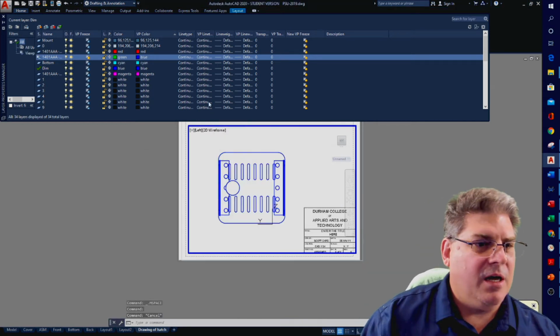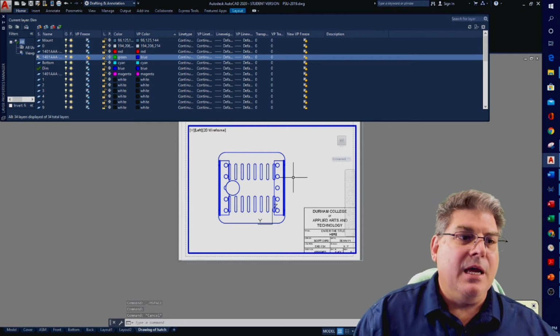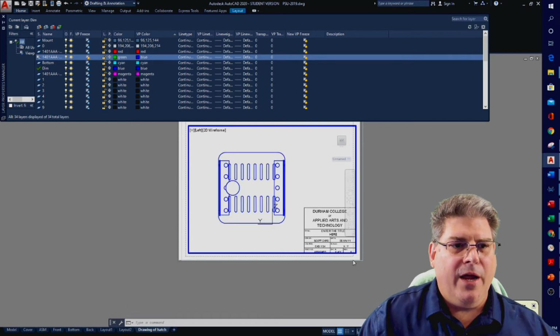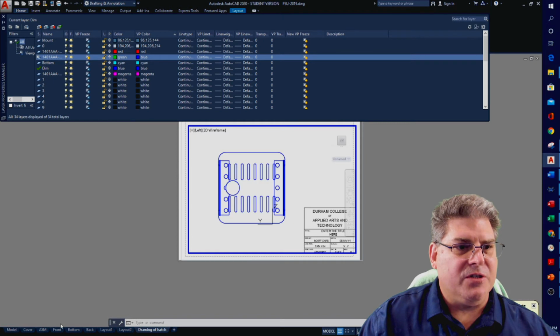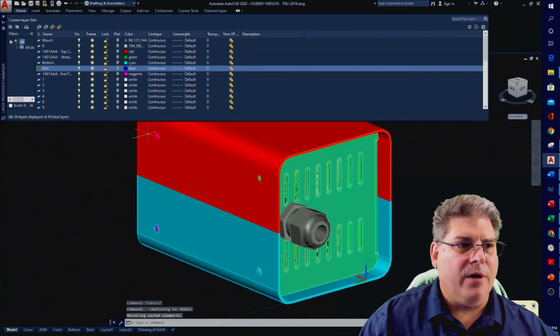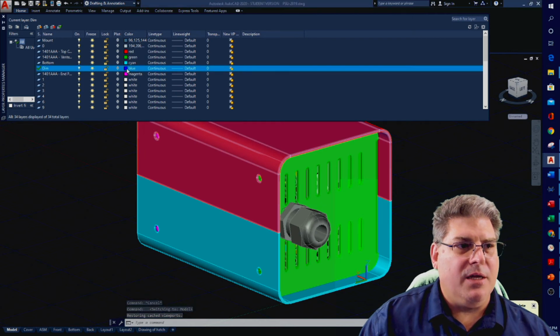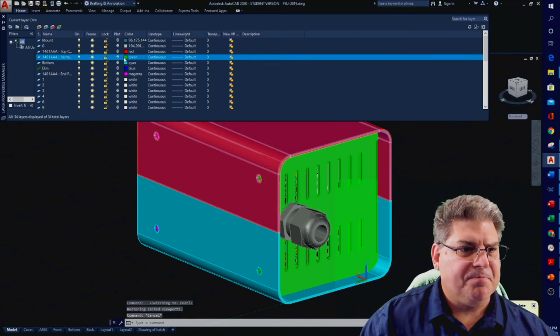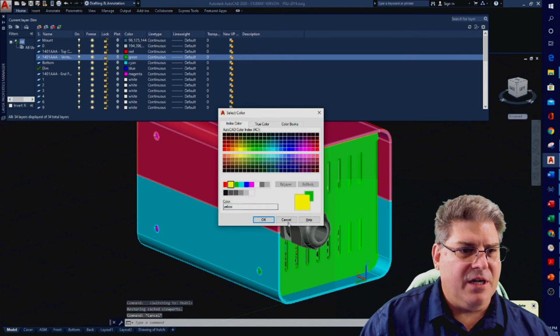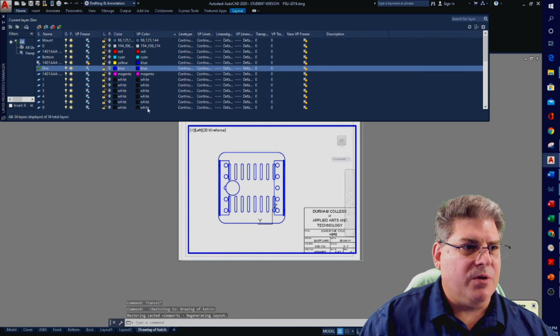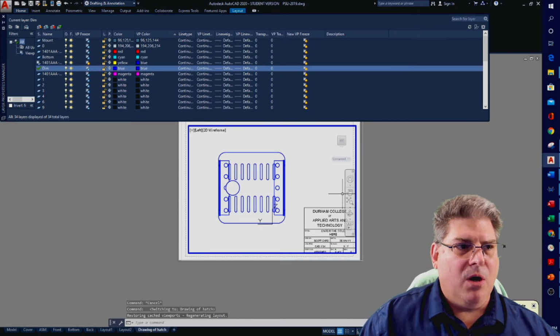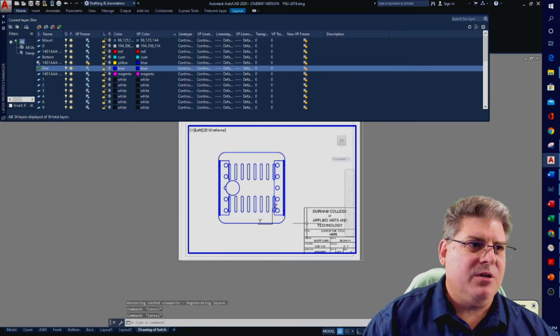Finally, the trick is that you need to be in your layout, set it to model space, and then you'll be able to change it. So it's blue here, and when we go back to our model, it's still green. Or you could change it back to yellow if you wished. There you go, nice yellow part. And we go back to a drawing of a hatch, and it's still blue. So yellow and blue. Changing colors for viewports is absolutely essential.